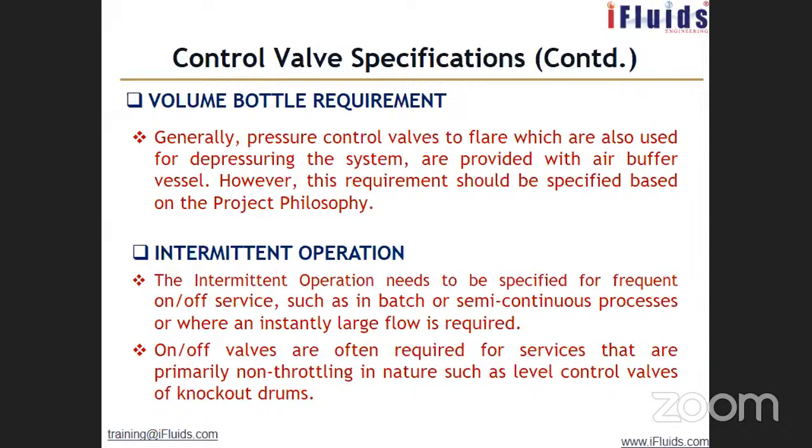It is connected to the level control valve, which will drain to the drain system. So once it reaches a certain high level, the level control valve at the outlet of the knockout vessel will automatically open. There will be some mechanical arrangement. There is nothing like a control measurement or level signal. Usually they are called automatic level control valves, so they act on a mechanical system.